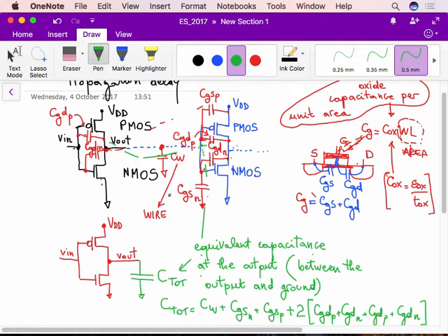And we can switch the logic gate, the inverter in particular, if we are able to charge and discharge that capacitor. So the smaller the capacitor, the easier it is going to be charging and discharging, so the faster we can go, and the more current we can drive at the output, the faster we can go. This is pretty intuitive. Okay? And of course, it is true for the inverter in this particular case, but in general, it's true for any logic gate, because all logic gates are working on the basis of the same operating principle as the inverter.